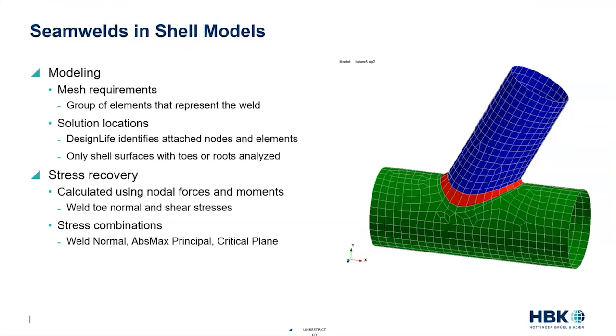And again, we're using structural stresses, in this case, from forces and moments, to allow us to get an accurate measure of nominal stress going into the weld and be relatively insensitive to the mesh. In addition, it's looking at multiple sets of forces. So we're looking at normal forces and shear forces in this calculation, and that allows us to use a variety of different stress quantities in our calculation, whatever tends to make the most sense for the loading conditions we're in.